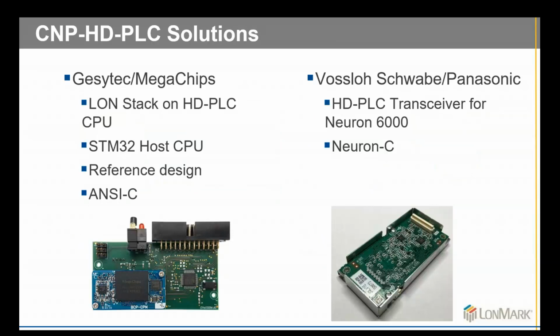We have two solutions available. The first one is from Gizitech and MegaChips. We have the LON protocol stack integrated directly into the HD-PLC CPU. So we made the HD-PLC chip from MegaChips to be the LON chip on HD-PLC. We are driving an end user's application on a serial attached STM32 CPU from ST. It can be any other CPU you can imagine.